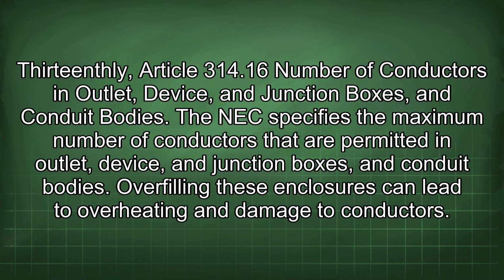The NEC specifies the maximum number of conductors that are permitted in outlet, device, and junction boxes, and conduit bodies. Overfilling these enclosures can lead to overheating and damage to conductors.